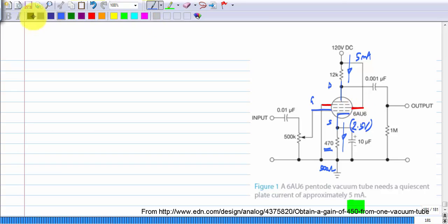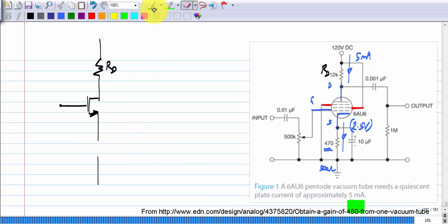Okay, this is one of the circuits that we discussed. This is the circuit where you of course have the drain bias resistor, which corresponds to this, and you would like to bias with a current source at the source terminal, but because current sources are harder to implement, you substitute a resistor instead. That's exactly what this is. Okay, so what we have here is a common source amplifier with a resistance in the source, which is standing in for a current source at the source of the transistor.